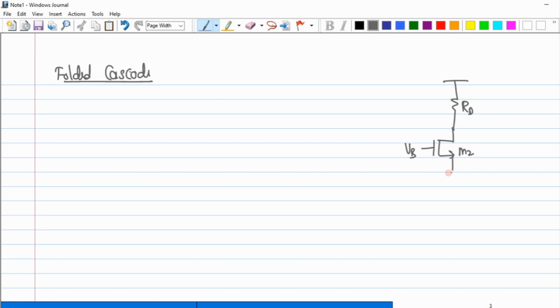If I put a source, the output impedance will be different, right? Because the impedance that I see, I still want to maintain as RO itself. I don't want to put a source over there and reduce that impedance further. I have to go with drain only. Okay, so yeah, you're right. I thought I would ask that question.